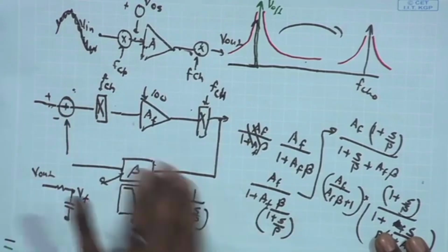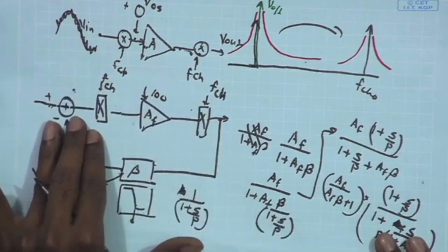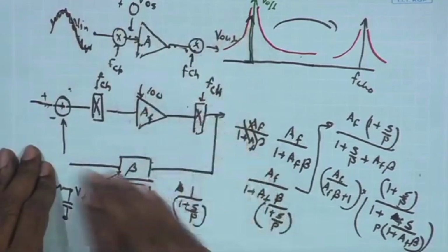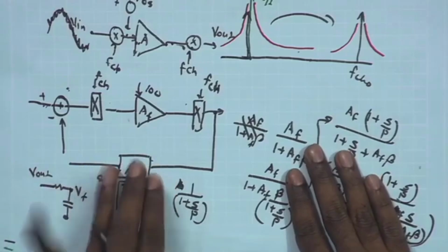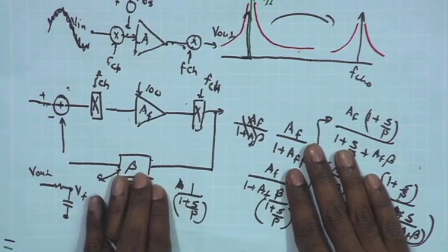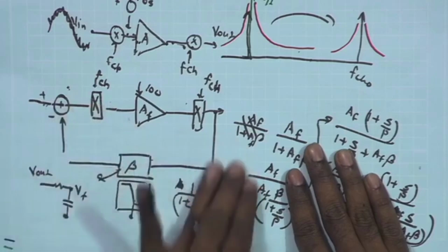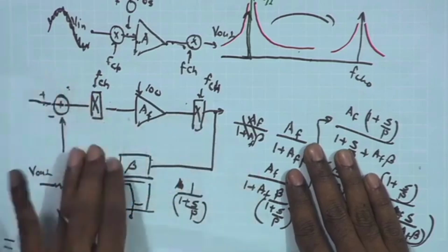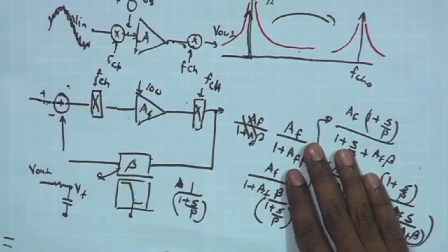So, the design of this loop becomes important, and we have to consider the overall feedback system, where we are trying to pass our desired signal and trying to block our undesired signal with the help of a desired beta factor. So, we need to look into this and see, first of all at block level, how do we choose the parameter for this beta network, and second at transistor level, how to implement this connectivity and ensure that while achieving low noise, we are able to reject the undesired signal.